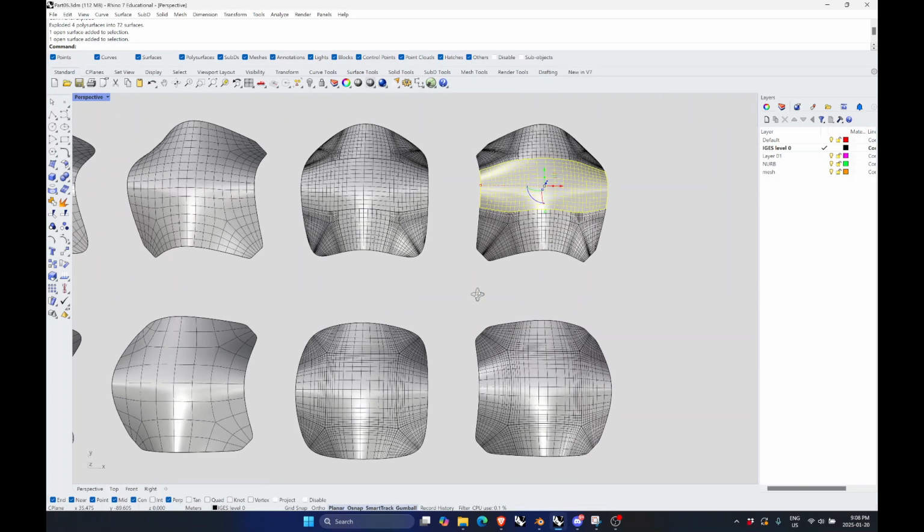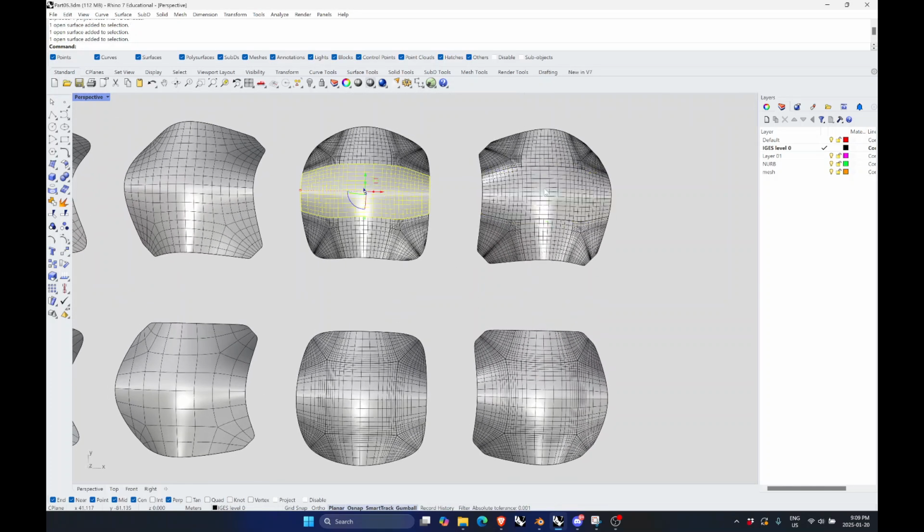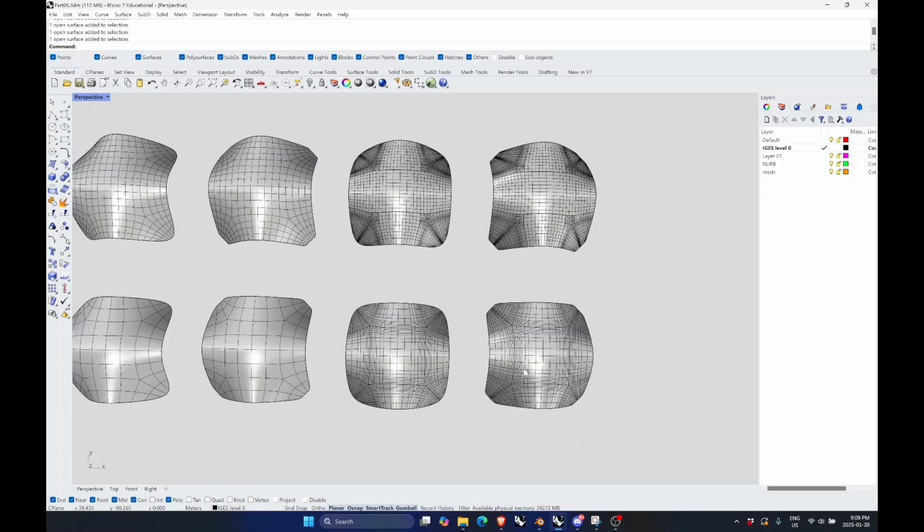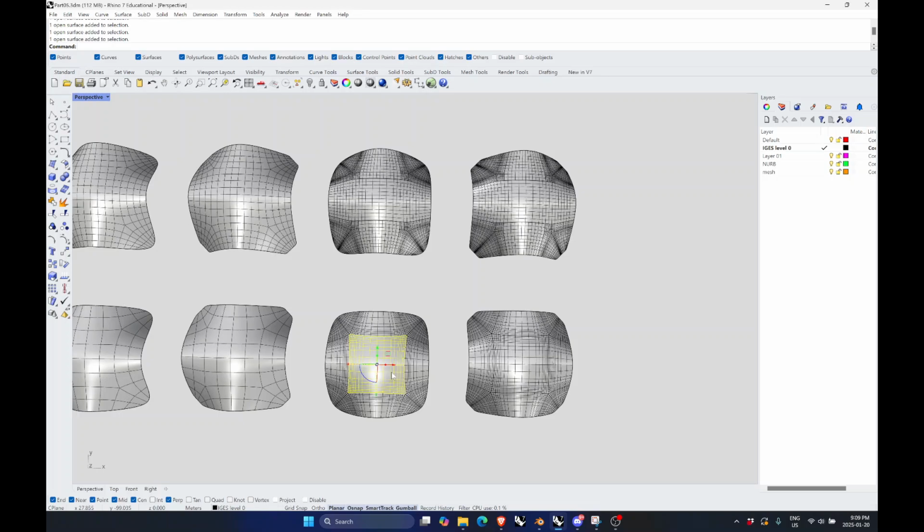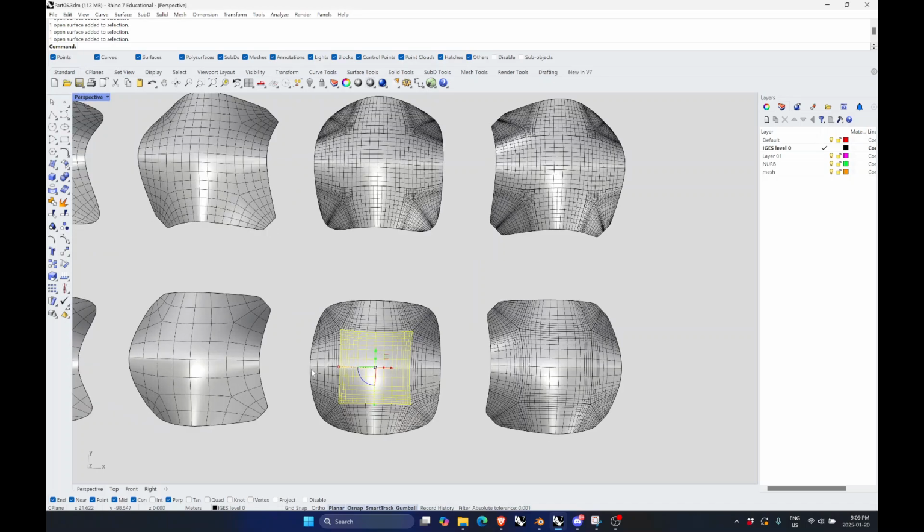Now, if you look at level 3 subdivision, when I click on this and this, you can see how it sort of spans from left to right. It's not really giving me a symmetry to work with in terms of topology as to how the computer is constructing it. But level 2 subdivision gives me a middle plane, and these surfaces along the sides.